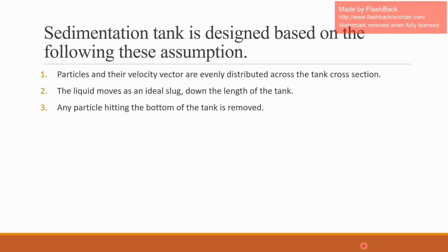Next one. Sedimentation tanks are designed on the basis of certain assumptions. So what are these assumptions? The first assumption is that the particles and their velocity vectors are equally distributed all across the tank itself. The next one is that the liquid in the tank moves along the whole length of the tank itself.